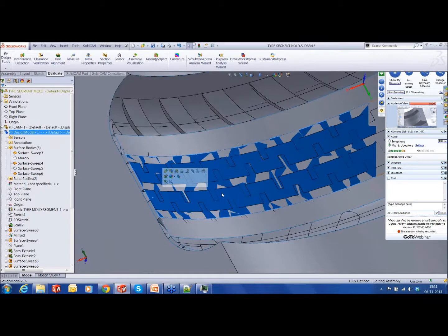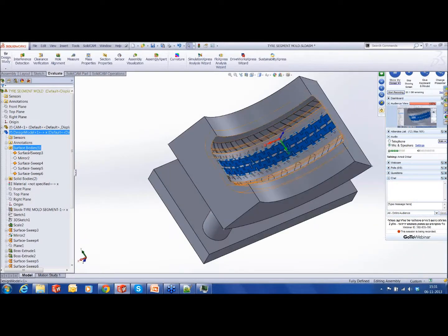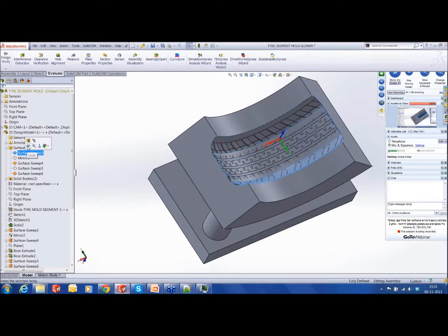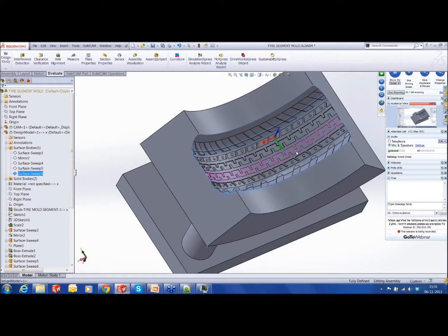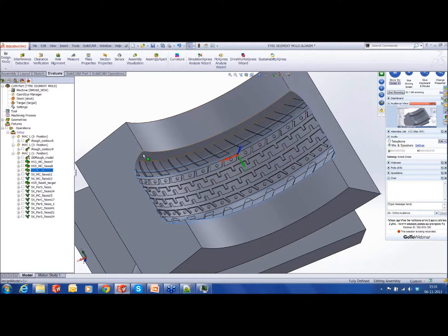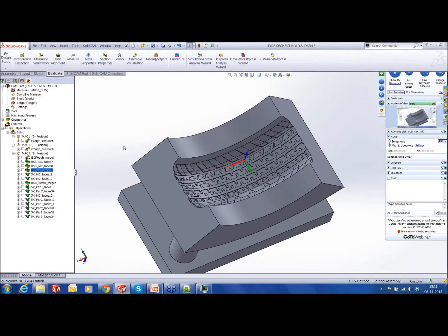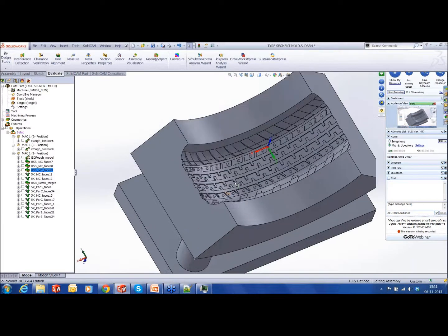So what I did was I roughed out the entire thing up to this surface without the projections. So what I get simply is some nice smooth surface from where I can start carving out these profiles using 5-axis. So once I have finished the machining of those surfaces, I can carve out. How did I carve out these toolpaths? I've shown in this case both the examples.